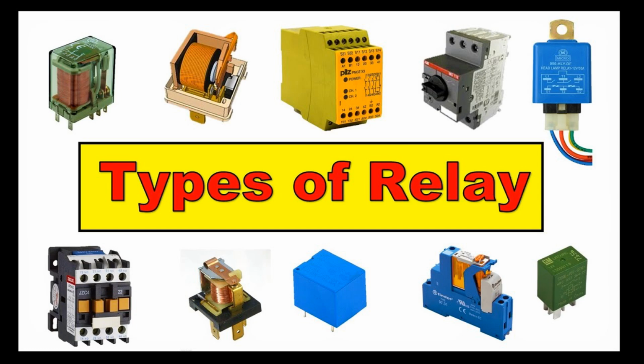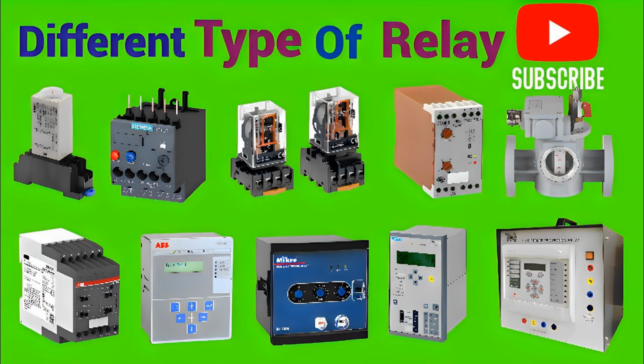Structure and components. Permanent magnet. Provides a constant magnetic field, which helps the relay respond to the direction of the coil's current. Electromagnetic coil. When energized, this coil generates a magnetic field whose direction is determined by the polarity of the current. Armature. A movable component that interacts with both the permanent magnet and the magnetic field produced by the coil. Its movement depends on the direction of the current.